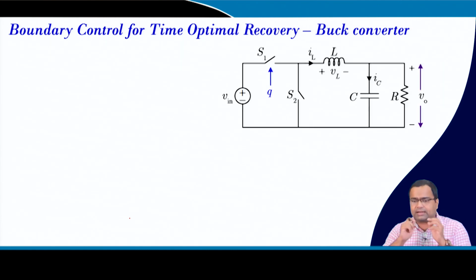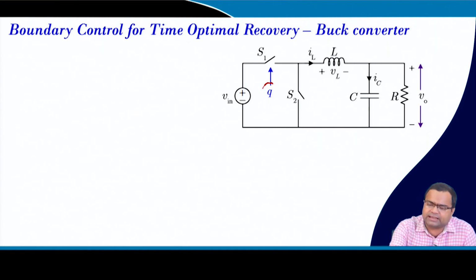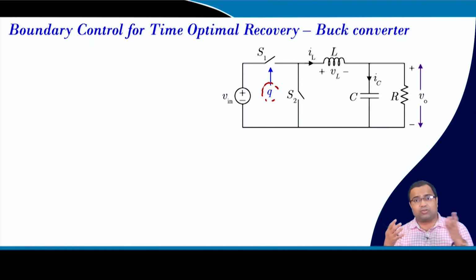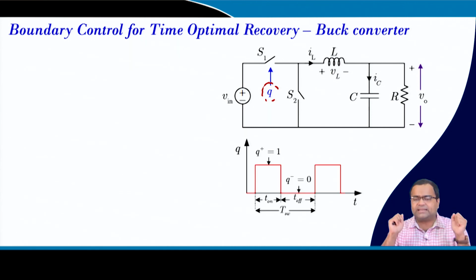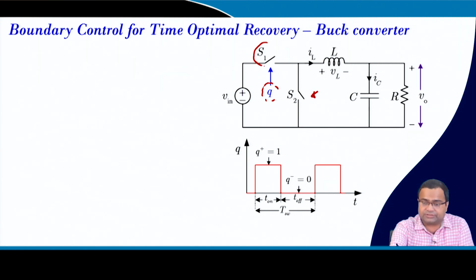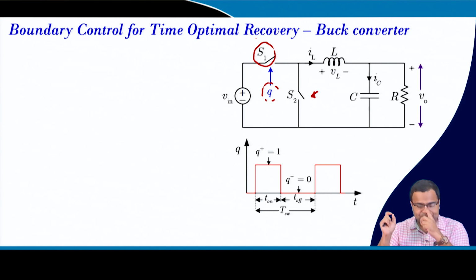Okay, so what is that? Let us consider a buck converter. Here Q is the gate signal, which is a controllable gate signal. Again we are assuming an ideal one, but you can always consider the dead time and practical parasitics, which we have discussed earlier. Here we are trying to build the concept fast. The objective is to turn on and off this controllable switch, because the other switch ideally is the complement of this high side switch, but practically there will be a dead time.